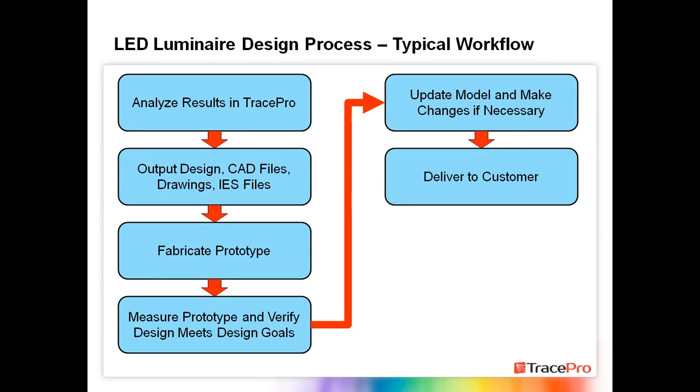In this case, I have setting up in the Optimizer. Then we could look to set the model up in this case, TracePro. And this would include the optic, the source, and the target. We then define our optimization goals and targets. What are we optimizing to? What is our goal? Then we'd run the optimization process.